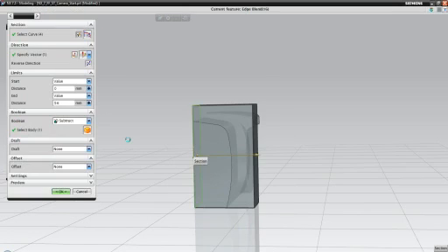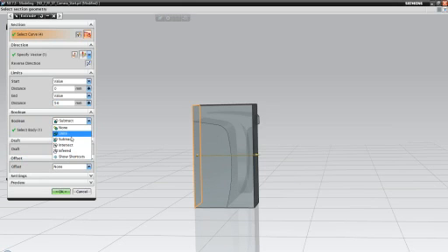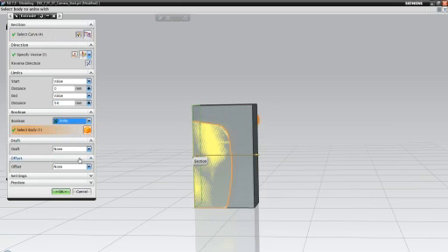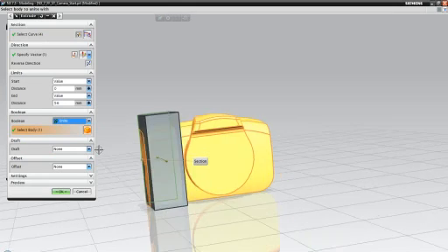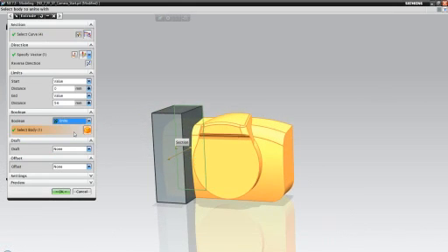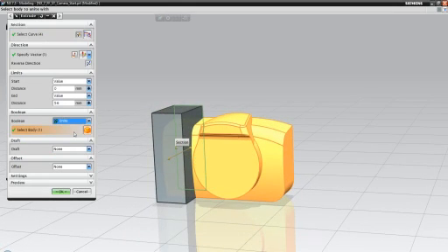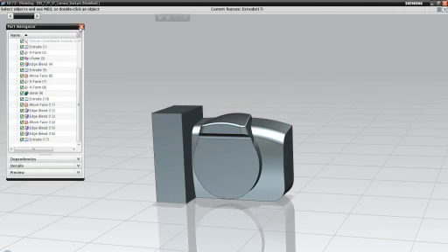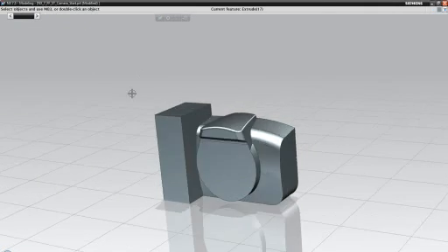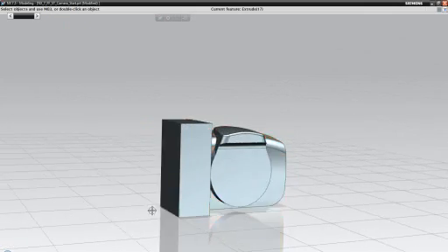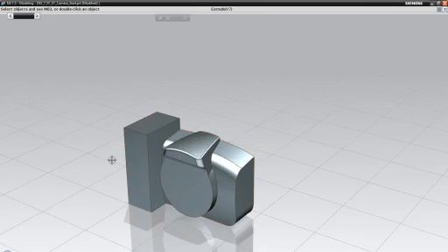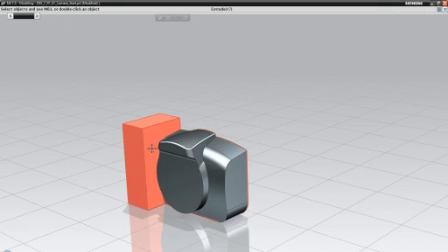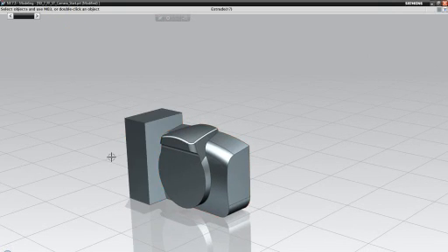You know, using synchronous, using the tools that are inside of NX, I can quickly come in and make that change. I don't have to recreate it. I don't have to undo it. I'm just going to go in there and fix it. Okay. So now you can see that I have my extension there. I'm going to jazz this up a little bit and make this a more comfortable feature.